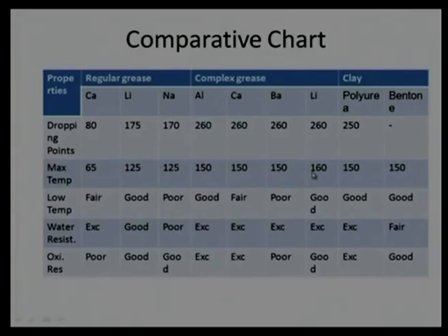Whenever the temperature is more than 150 degrees centigrade, we should switch over to some lubricating oil which has heat carrying capacity, or heat dissipation much faster compared to greases.